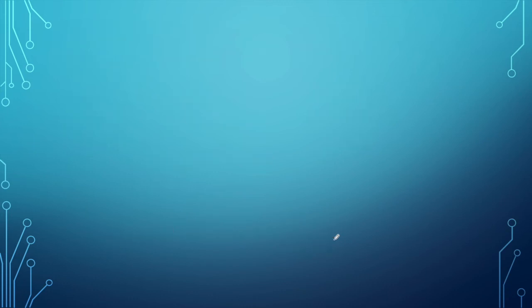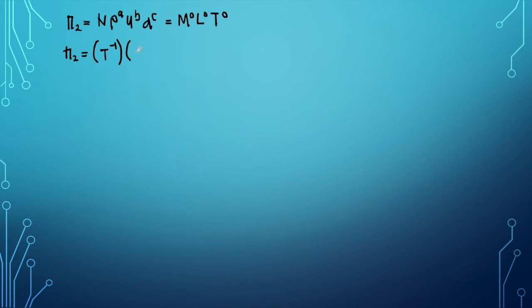Let's move to the second pi. Pi 2 is revolution n times rho power of A, U power of B, D power of C equal to M power of 0, L power of 0, T power of 0. Then substitute dimension. So dimension for n is T minus 1. So dimension for rho is ML minus 3, power of A, U is LT minus 1, power of B, D is L power of C, equal to M power of 0, L power of 0, T power of 0.